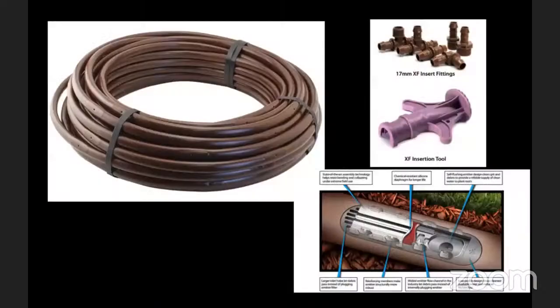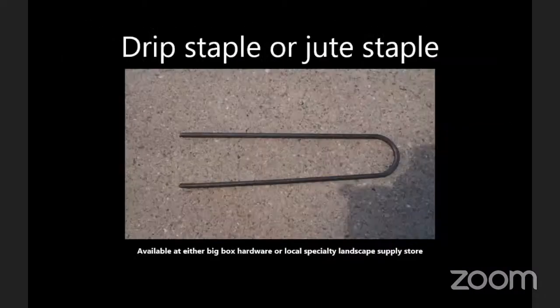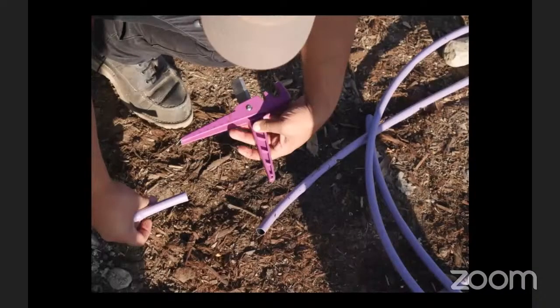And then from that header being installed, then when you install the actual tubing, so that's this stuff. Oh, and here we go. Here's the picture of the staple. And so the tubing, which again here is only purple because that's what we need to do for our recycled water, cuts. You can use a normal PVC cutter or even a very sharp garden shears. Very sharp garden shears is a decent way to go.